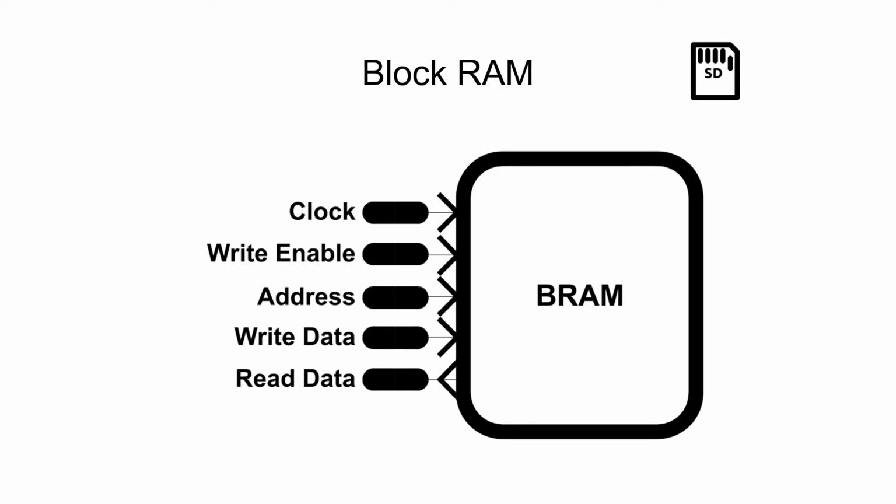The second common form of storage in an FPGA is BRAM, which stands for block RAM and is an FPGA primitive. An FPGA primitive is an HDL object that corresponds to a physical portion of silicon within the FPGA. BRAM can be used for large amounts of addressable data that can be non-sequentially written to and read from memory, but only one word at a time. The word length for BRAM can be varied depending on the FPGA used, where word lengths greater than 512 bits are not unheard of. Greater word lengths can be achieved by using multiple BRAMs simultaneously in parallel. This can allow for substantial amounts of data to be concurrently written to and read from memory.